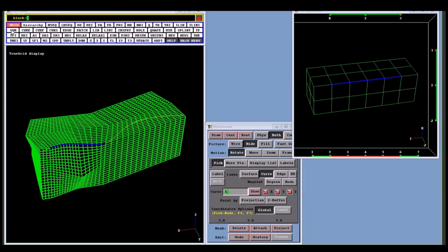Getting back to the mesh menu, I want to point out that we now have another 5 commands that all work basically the same way, attaching an edge of the mesh to a curve or an edge. So I think the best way to summarize it is attach is when you change the initial position of part of the mesh. And that initialization then is what the projection method will use when it goes to project the mesh to whatever surfaces you've selected.